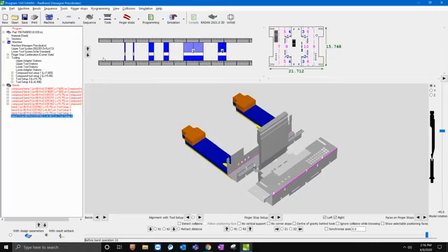So another good thing about Radbend is if you're a designer or an engineer and you're working in the office, you can actually come in and check your design before you even get it to the shop floor, right? So, maybe I need to modify that, jump back into 3D, stretch that flange out, move this flange a little bit, and then run it back through the software to simulate it and make sure it goes to where it needs to be, okay?